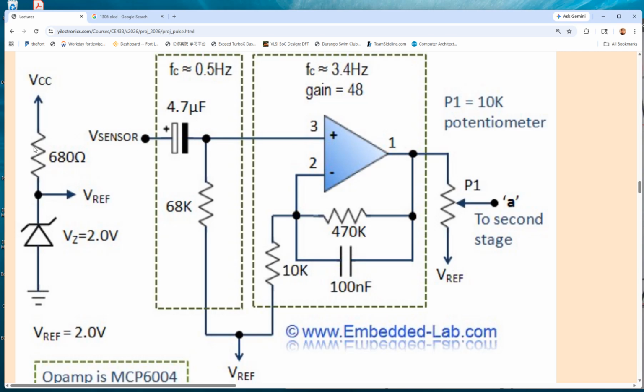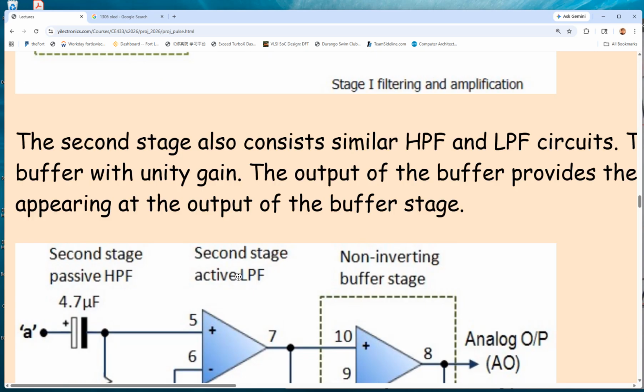You just don't solder these 2 components. Just leave it open, so VCC cannot get to this point. Also leave this open so ground cannot get to this point. Then you find a metal piece, it could be a pin, and you solder a wire to it, and eventually connect your 0.5 volts to this point, so the 0.5 volts will be delivered to the VREF. Okay?